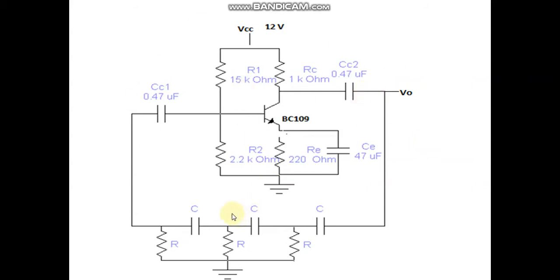So you only have to do the design of the frequency, and the design of the transistor is not mentioned in the syllabus. But you can have the voltage divider biasing. We make use of voltage divider biasing so that you get a stable output for the transistor, that is, the Q point is stable.